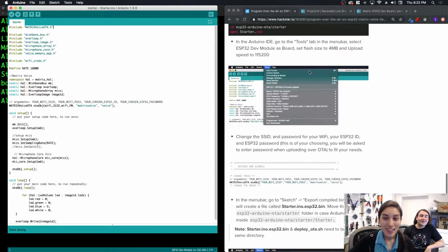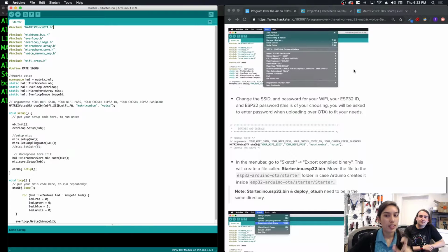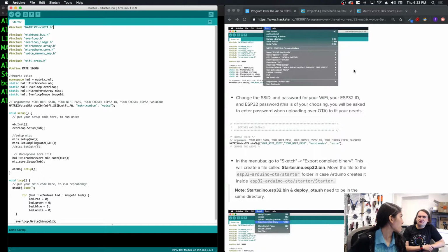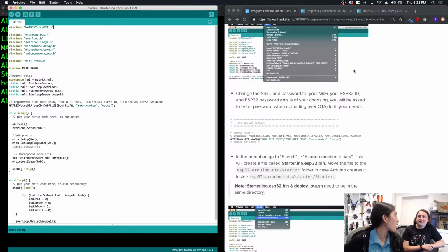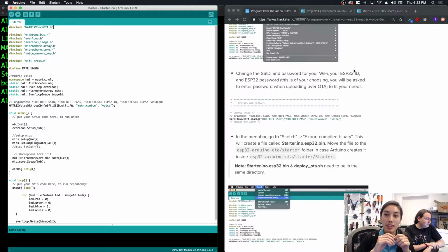Let us know if you want a guide on how to do that. Yes, that's actually a good guide to set up. It's simple if you have the device. I don't think it's that expensive. The FTDI is probably maybe $5 or $10 on SparkFun. It's nifty. You just connect a couple of pins, and then you can see in your terminal anything you Serial.print. But you actually can't use the serial monitor over Wi-Fi, unfortunately.